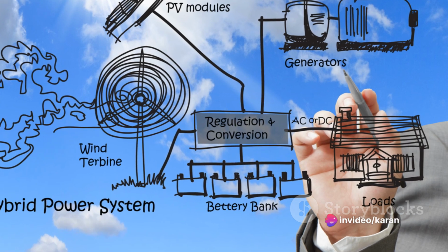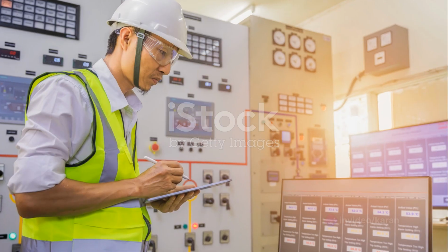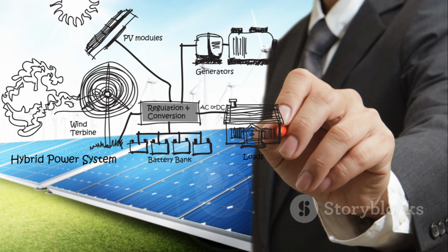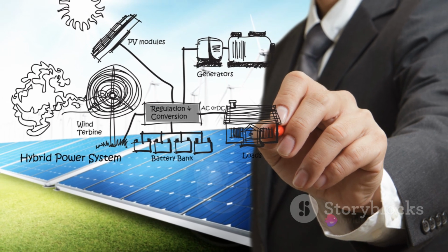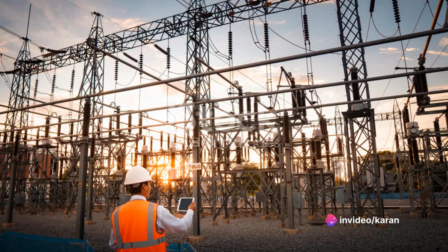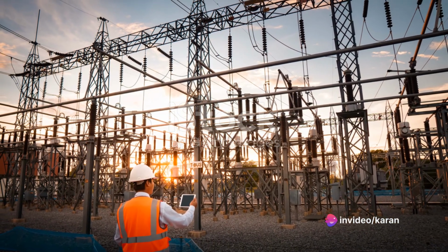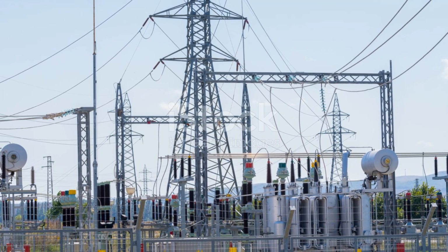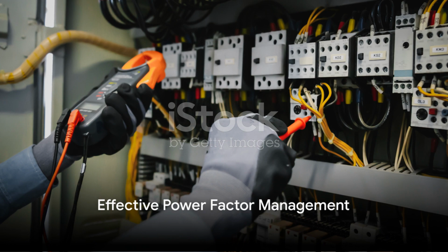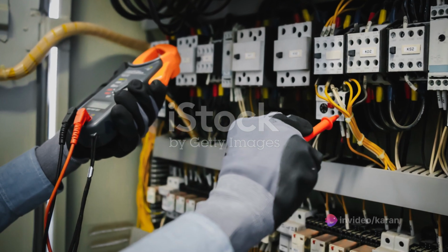By understanding these factors, inductive loads, capacitors, and harmonics, we can start to see how we might manage our power factor more effectively. Whether that's by reducing the number of inductive loads, adding capacitors to the system, or ensuring a clean power supply, we have several tools at our disposal. Understanding these factors can help us manage our power factor more effectively.